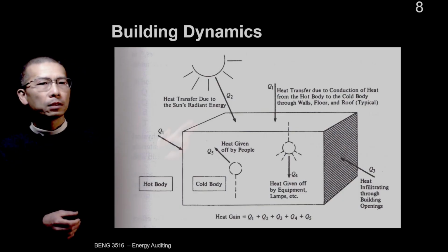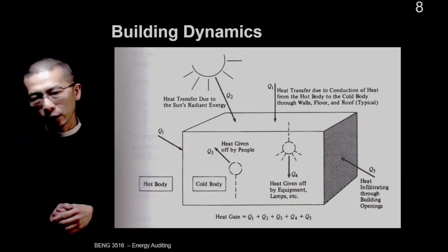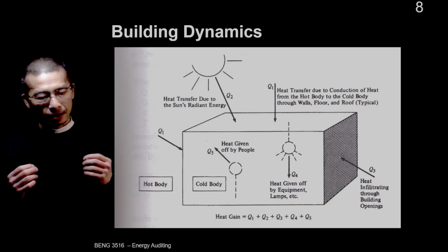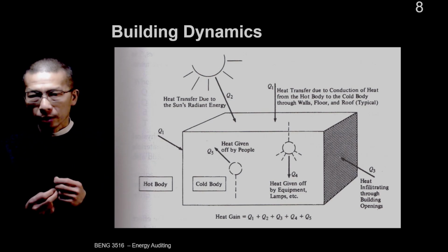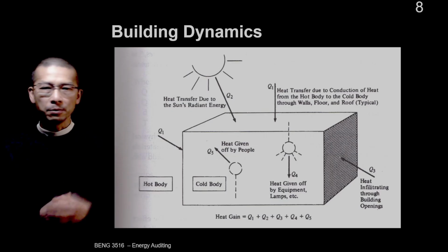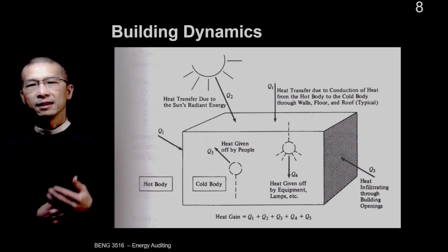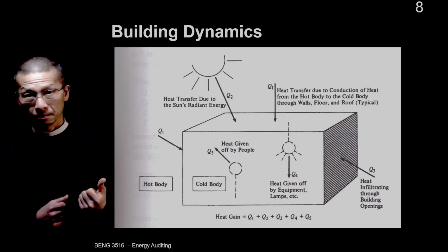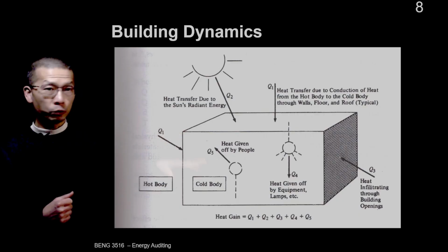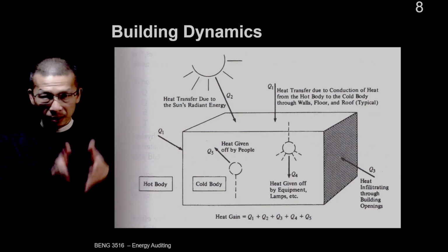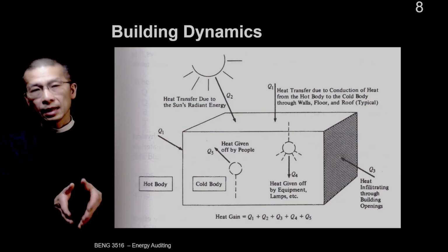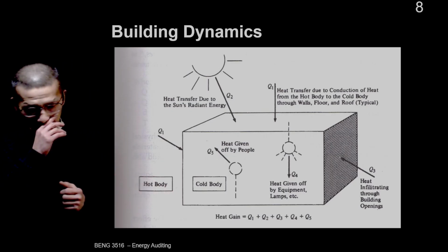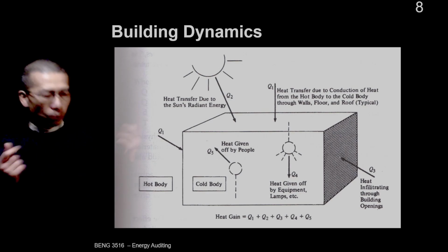Also, Q2 here, solar radiation. This is often the largest variable. It is the direct energy from the sun hitting the glazing area and absorbed by the roof. So part of it can be direct, and also through the solid envelope in general, the walls, it will come in slowly, and therefore it's a transient problem. Okay.